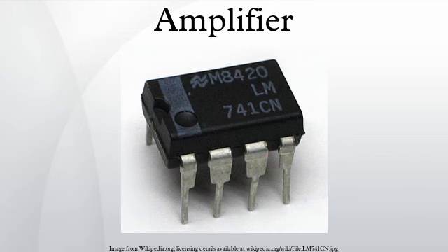Conduction angle classes. Class A: 100% of the input signal is used. The active element remains conducting all of the time. Class B: 50% of the input signal is used. The active element carries current half of each cycle, and is turned off for the other half. Class AB: Class AB is intermediate between Class A and B. The two active elements conduct more than half of the time. Class C: less than 50% of the input signal is used.